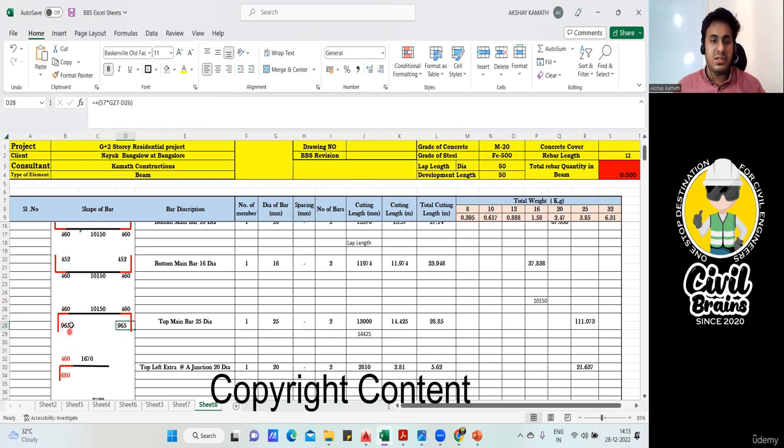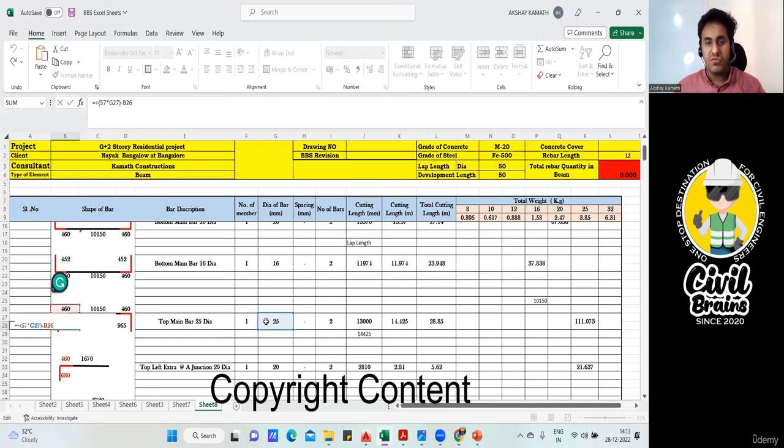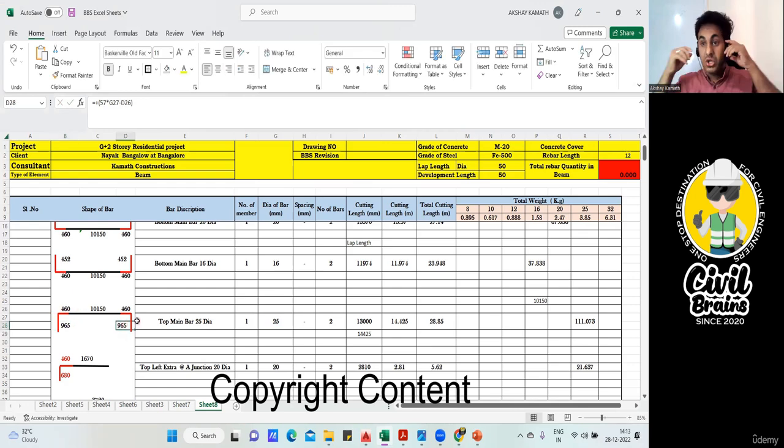So the same thing I've done here. How did I get 965? I've done 57 into 25, 57 into 25 minus 460. If I do, I'll get 965 and 965. You do it manually. Later, you can input the values in the Excel sheet. Finish. Your answer is ready. Again, number is 1. Dia of the bar is 25. We require 2 bar of 25.